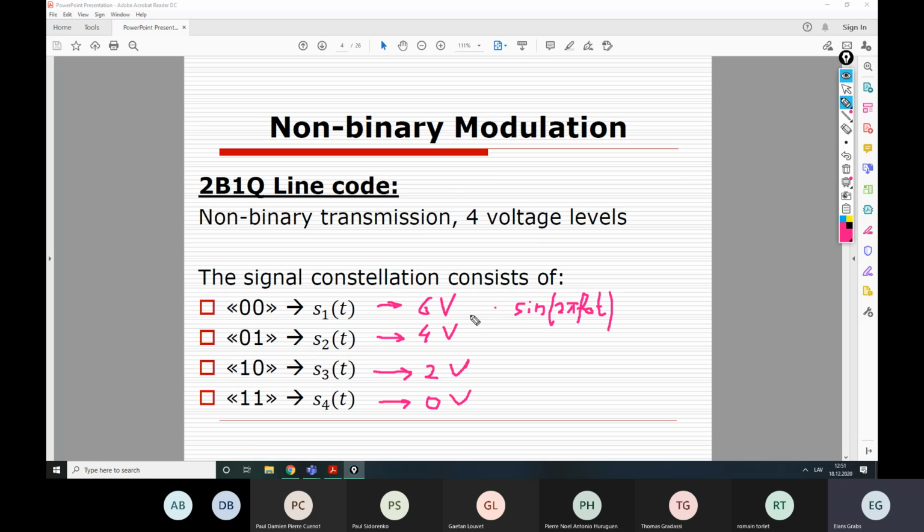And each of these 4 signals with different amplitude now carries 2 binary symbols, 2 bits of information per each, right? So as you can imagine, nothing is stopping us from making 8 different signals, and then we can put 3 bits and send them with the same time duration as before, right? So basically now we can transmit data twice as fast compared to, for example, binary amplitude shift keying, which is good. And actually, that's not where we are going to stop.